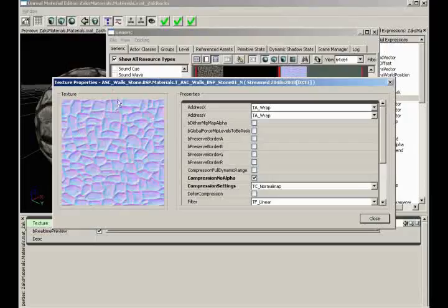It almost looks like a red light was shined from the top, that a green light was kind of shined from the side, or do I have it wrong? No, I think I'm right. And then a blue light was shined from dead on. It's kind of hard to say because we have such round areas, so it's a little tricky to see where the light's coming from. But essentially, you can think of this as if light was shined from all 3 of the primary axes, from X, from Y, and from Z. And from the resultant color information, you get a clear picture of where crevices, where changes in elevation take place along the surface. That is how a normal map works.